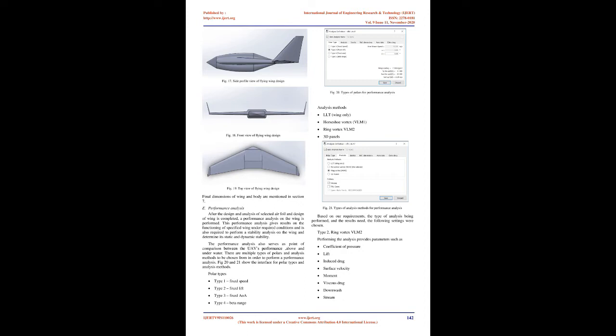To further facilitate better dynamic stability over a wide range of Reynolds number, a flap was added to the trailing edge of the foil. A flap of 0 and 5 degrees was included. Further analysis was performed on these foils to learn their effect and choose the best option. Fig. 6 and Fig. 7 show the 0 and 5-degree flap, while Fig. 8 shows the interface.